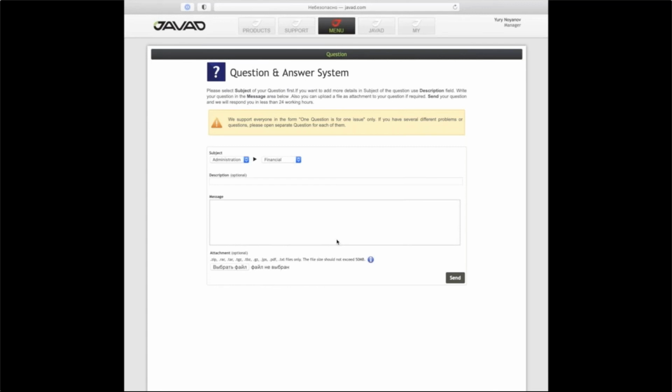There are two items in the question. One is using VRS, and another is using NAD 83. The first is to feed VRS results into our RTK. The VRS can include other manufacturers' equipment, and in that case JAVAD receivers have many tuned settings. But the settings are better set up with low-level setup scripts or with NetView software.